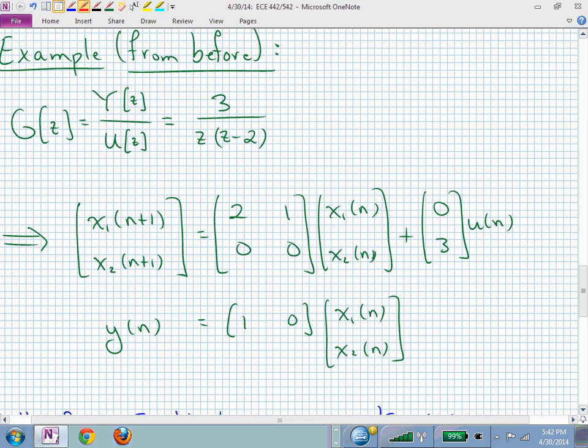Is it stable? Open loop, is that system open loop stable? Why not? It has one of its poles outside the unit circle, and all it takes is one, isn't it? Can you stabilize this system with output feedback based on your knowledge of the root locus?